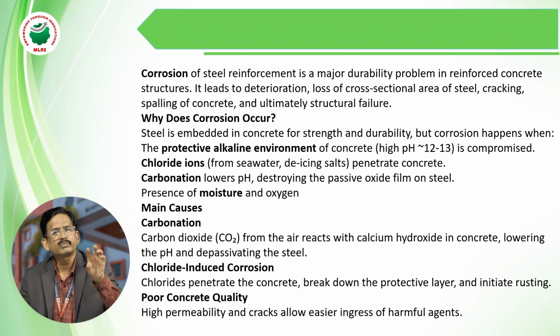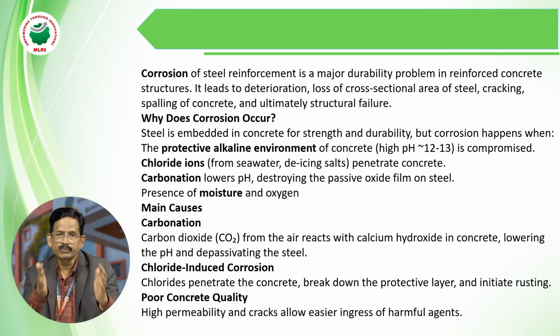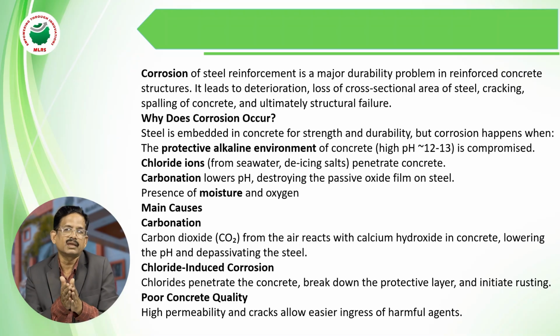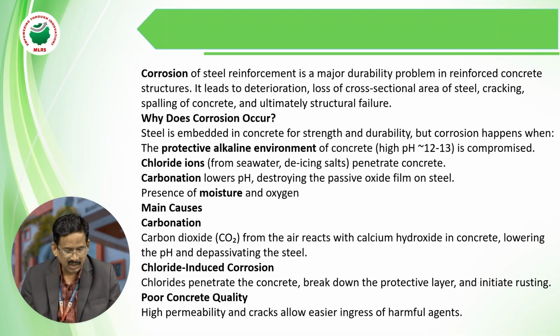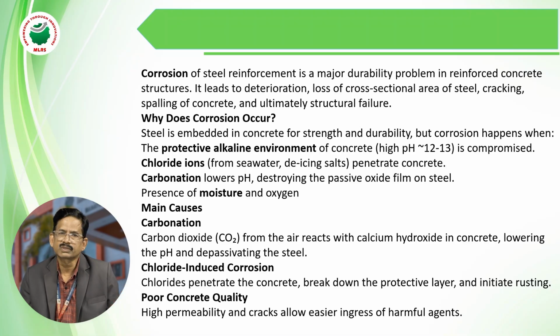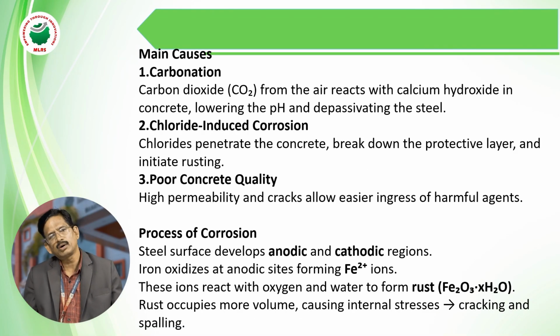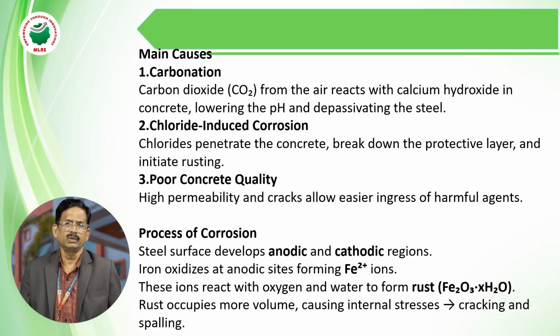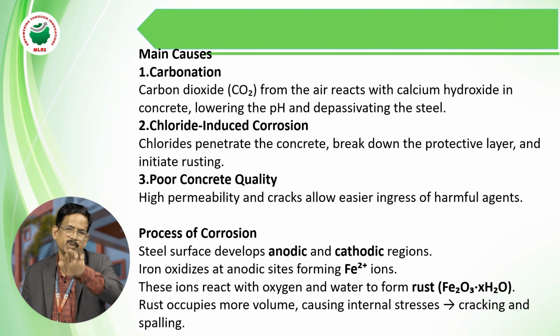So that's why sometimes the structure will be deteriorated, not collapsed at a particular time. It will be deteriorated. So that's why we have to take utmost care against the corrosion of the steel reinforcement. Carbonation also occurs and corrosion also occurs, because of the poor quality of the concrete too. So we are not blaming only the steel reinforcement failure. We have to take care about the concrete quality also.